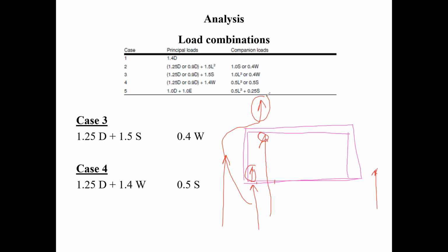Okay, and that's what you have to realize: you're right. If you leave all your doors and your windows closed and you never open up a window, the internal pressures are very little. But can it happen on a windy day? All of a sudden you open up the window, right? You open up the window and you get this gust of wind that comes in here and pulls the wind away from this wall, pushes on this wall. And then as the external ones are going around your building, they're pushing on the outside, pulling on the outside. And that's what it is, Alex, you understand?